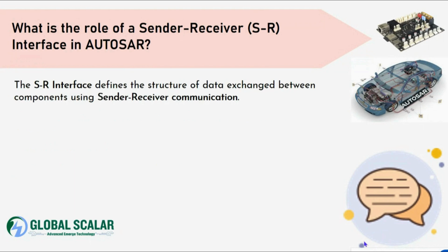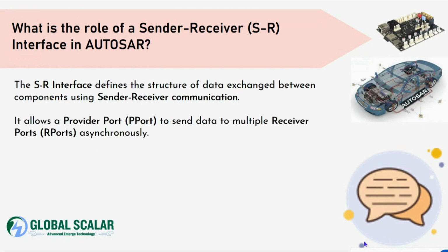What is the role of the sender-receiver interface in AUTOSAR? The SR interface defines the structure of data exchange between components using sender-receiver communication. It allows the provider port, PP port, to send data to multiple required ports, RP ports, asynchronously.